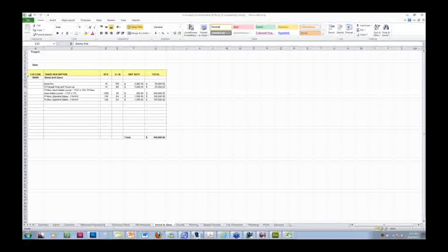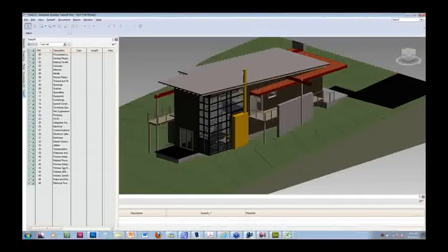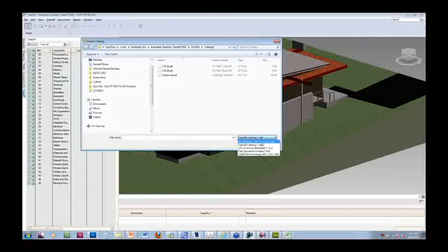You can do the following. In QTO, if you were to start from scratch, or at some point without using this, you could go to import catalog, and what you could do is import CSV or TXT. So pretty much you can have a comma delimited file that can be saved from Excel, or you can have a text file that can also be comma delimited.